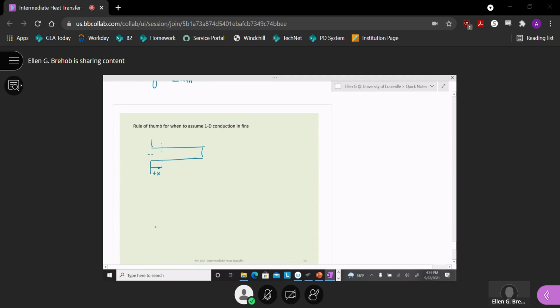temperature only a function of x. If I think of this as temperature increase and I'm looking at a particular location, you would imagine it actually does cool down at the outer face as I've got convection off of it. But our assumption is that the change in the y direction is so small because it's usually a high thermal conductivity material. It's a pretty thin fin. We want to get lots of surface area. So you could do 2D, but this is a simplifying assumption. We get analytical results.